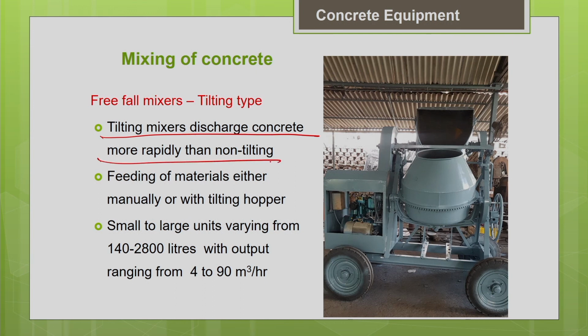Particularly for concrete, time is very critical. Once you prepare the concrete, once you add the water to the cement, the cement will start setting. That's why, as early as possible, we should place the concrete in the desired position. That is very important with respect to concrete.